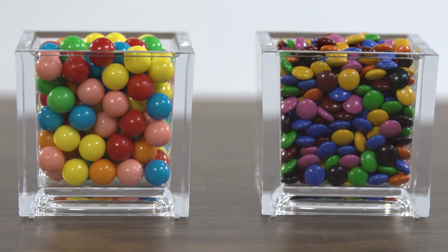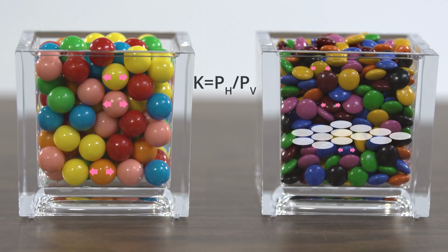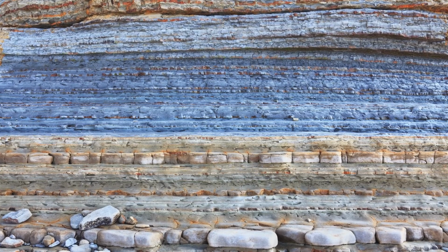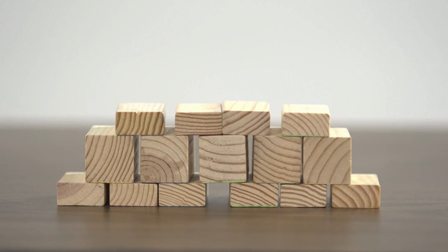The shapes and packing of the particles in a granular material affect the contact angles between them. Those angles and the coefficient of friction between adjacent particles determine the magnitude of the outwards pressure pH that is generated, and so they affect the value of K. If these ellipsoidal candies laid mostly horizontally, they would produce less horizontal force than if they were randomly placed or if they were spherical. Also, if the surfaces of either kind of candy became sticky, the lateral force would be reduced. As an extreme but practical example, sedimentary rock sometimes contains horizontal layers like those formed by these wood blocks.